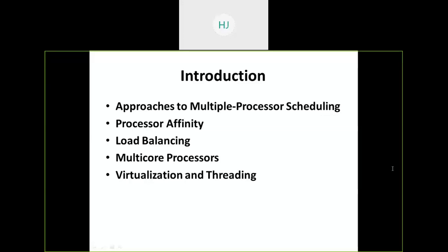Because of the delay caused by the long latency, the processor must switch to another thread to begin execution. The cost of switching between threads is high, as the instruction pipeline must be terminated before the other thread can begin execution on the processor's core. Once this new thread begins execution, it begins filling the pipeline with its instructions.